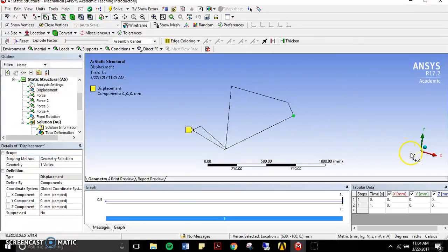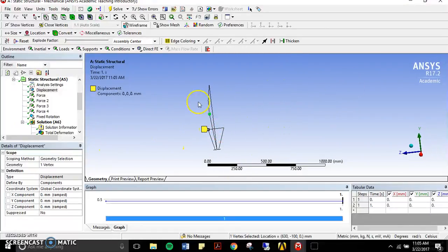Okay, z-wise displacements. Well, there's nothing in the z direction, so there shouldn't be any reason we can't just chuck it there, right? So think about these forces and how significant they are to our analysis, and whether or not you can just not put too much thought into that particular constraint, or whether or not you need to translate the stress through the entire frame. And if, for example, it's like the z displacement, where there are no forces in the z direction, it doesn't really matter where you put it. It's fine.